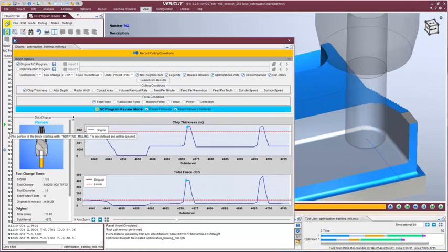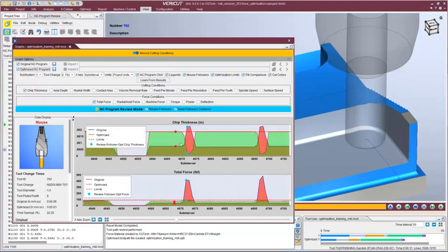One more time, and then right here where it hits the wall at a 90-degree angle, it opens up a cut around the face of the cutter, which is where all of the chip thickness was increased, and so were the cutting forces. And that's usually going to present itself as chatter marks in the corner. Some programs have a slowdown feed rate for corners. This one obviously didn't. So what did Force do with that? That's where it had to reduce the feed rate.